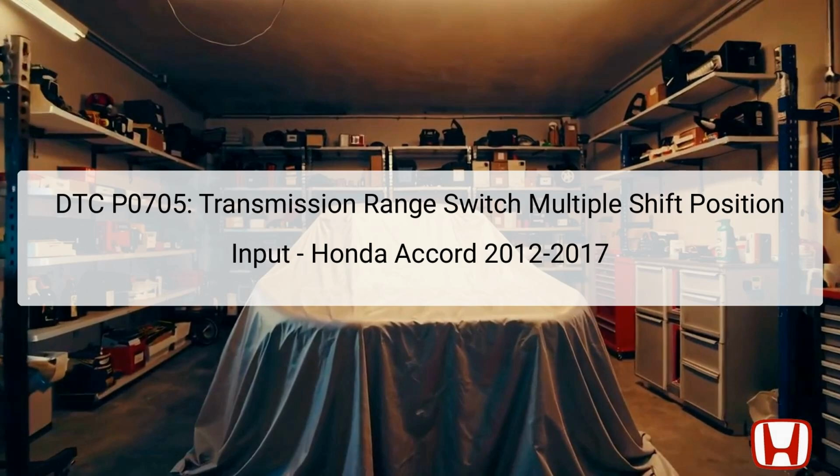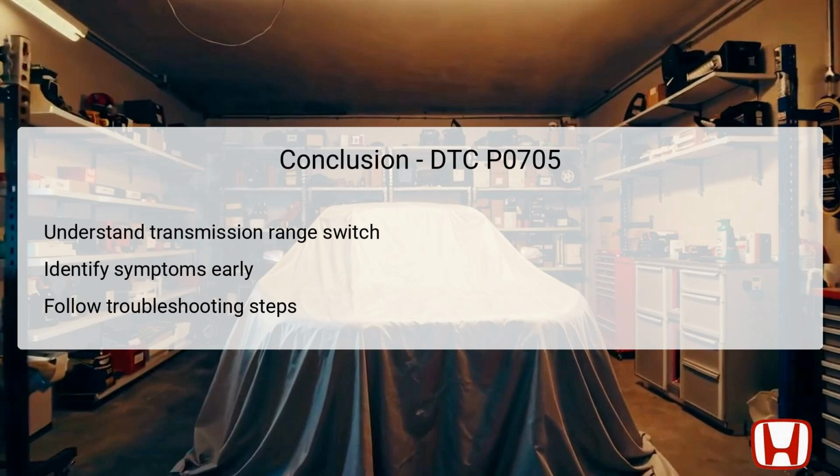The PCM uses this input to determine the appropriate shift schedule for the vehicle's continuously variable transmission, CVT. Failure in this system leads to potential shifting issues, affecting overall drivability and vehicle safety. Understanding the role of the transmission range switch and its connection to the PCM is essential for effective diagnosing and repair. In summary, understanding the role of the transmission range switch is fundamental to diagnosing DTC P0705 effectively.